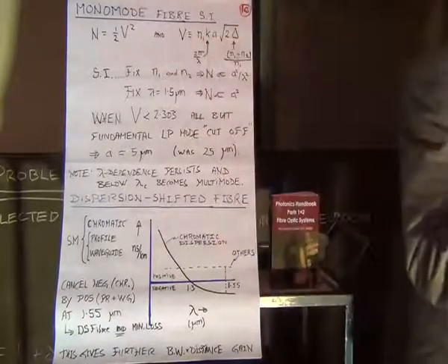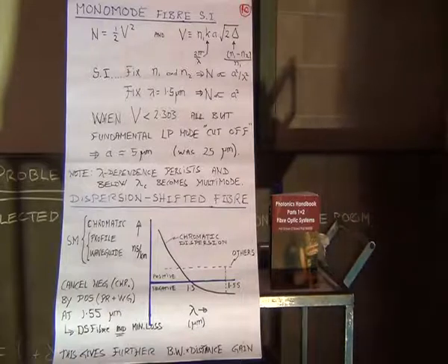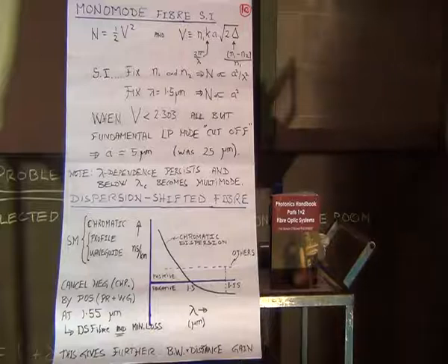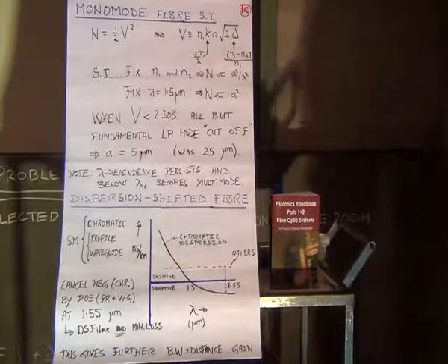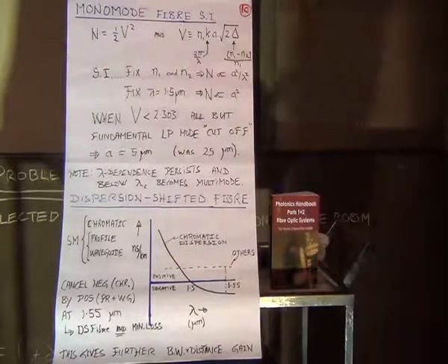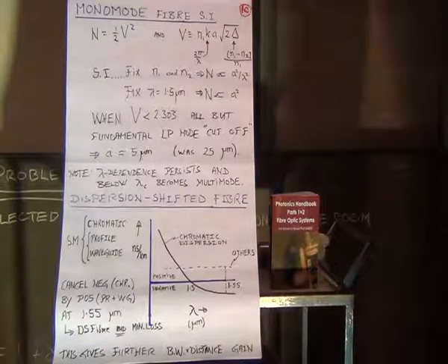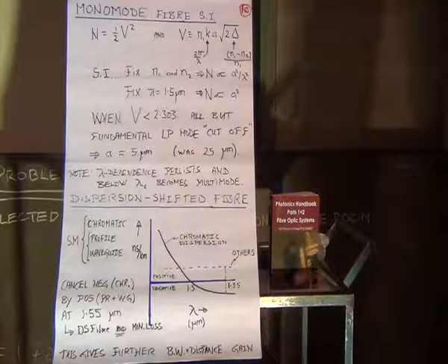In actual fact, it's the back of the book, you don't have to worry about it, but there's a kit you can use to measure modal dispersion in fibre. And I discovered the trick they were using, the people who manufactured the kit, was they were actually providing a transmitter which was shorter than the cutoff wavelength. So they were using single mode fibre, but the laser was just shorter than the cutoff wavelength, so it had become multi-mode, but not too multi-mode, just enough for a fourth year experiment or something to be able to measure the modal dispersion.